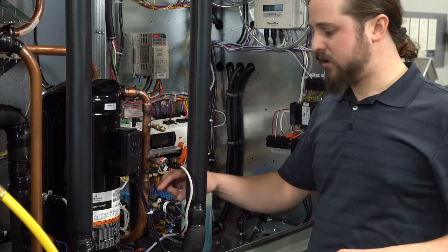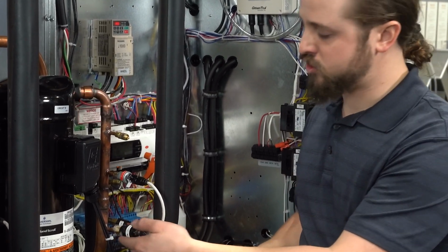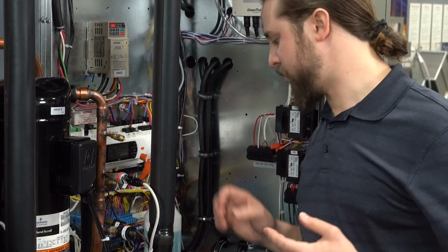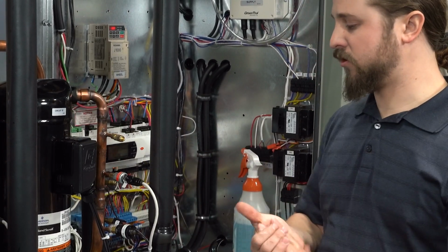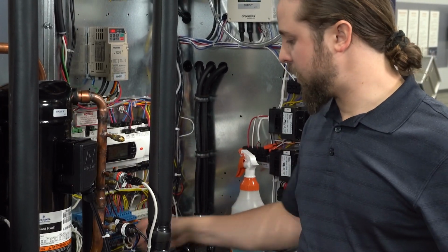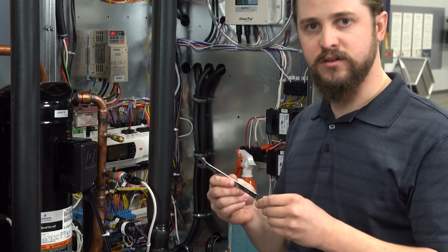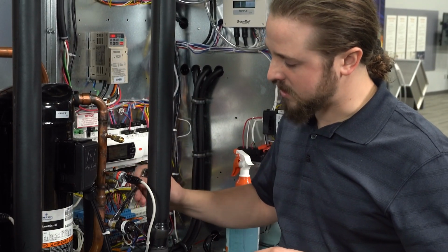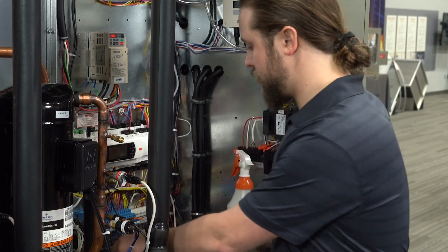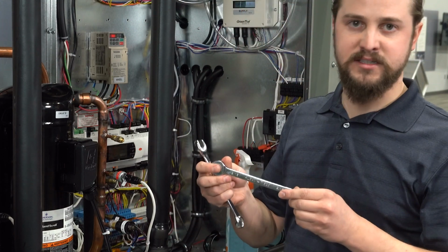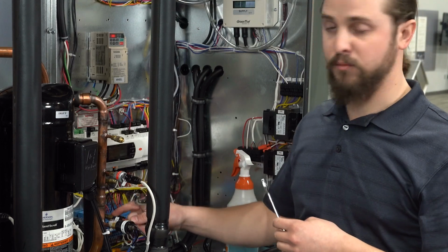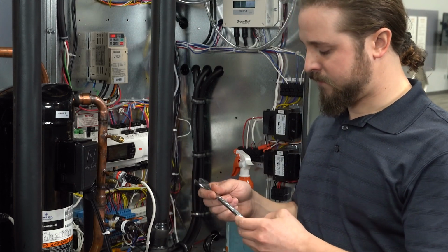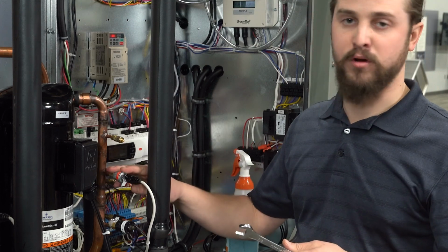Now, another leak that we have here is on a pressure switch. You can see here we have a substantial amount of bubbles developing. Now, the tools that you're going to use for that will be a 7/16 inch wrench. That'll be a backing wrench for the Schrader core side itself, and a 9/16 wrench for a low pressure switch and your high pressure switch, and a 5/8 inch wrench for any of the pressure transducers.